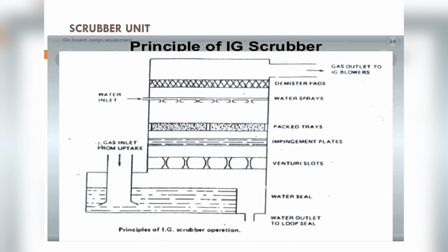So when the gases pass through the pool of water, some cooling is done and some solid particles are already removed from the flue gas. After that, it comes out from there. It is hanging above the bottom at a certain distance so that it bubbles through the water.